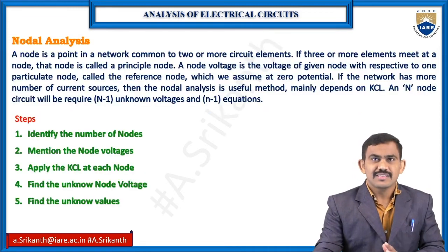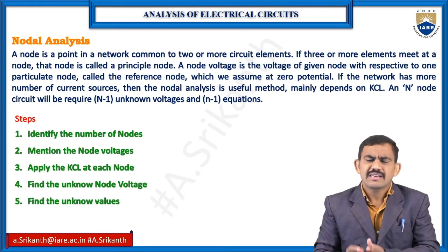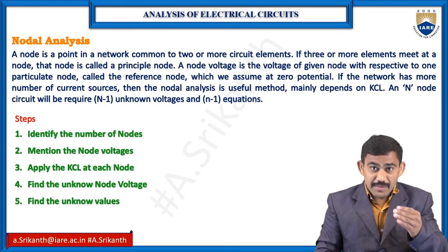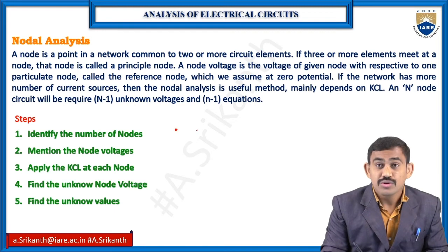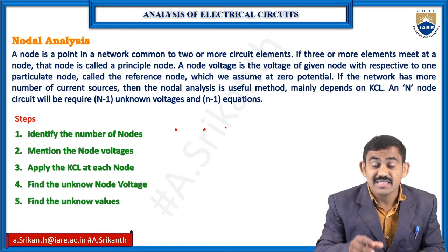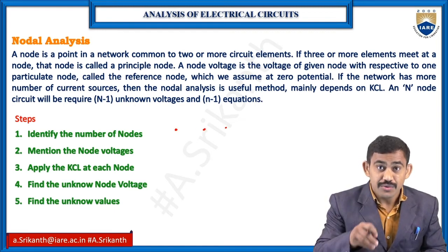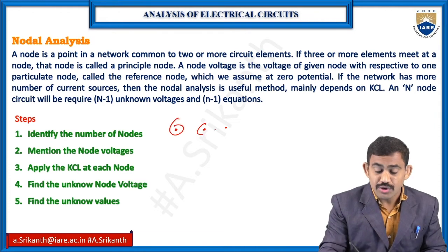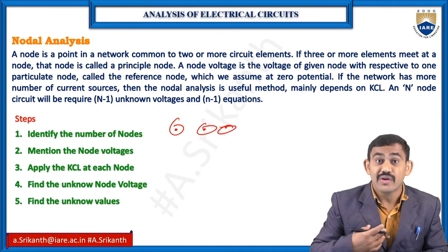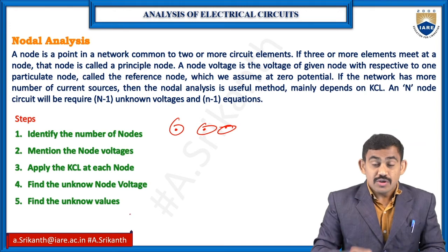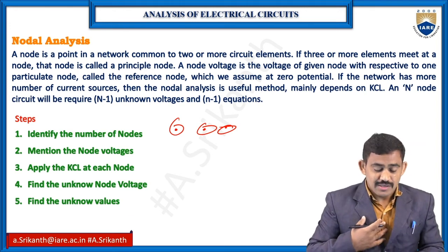Coming to nodal analysis, same procedure. In mesh analysis we have loops; coming to nodal analysis we have nodes. We need to mention the nodes, how many nodes we have. For particular nodes, I need to find the voltages. So we have the steps.